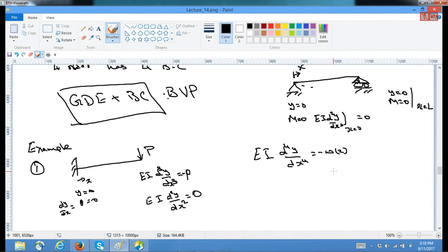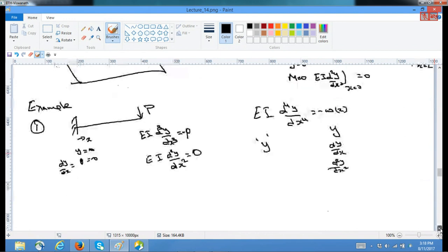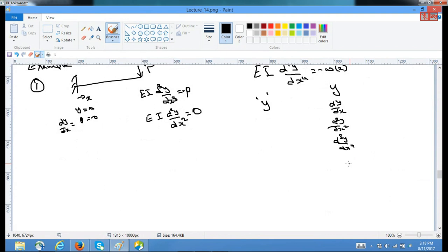But anyway, the thing I want to convey from here is that any solution y you are getting analytically has 4 requirements. That is, y has to be continuous, dy by dx has to be defined and it has to be continuous. That's the reason d square y by dx square also has to be differentiable. So continuous and differentiable means that if only y is continuous, it is C0.